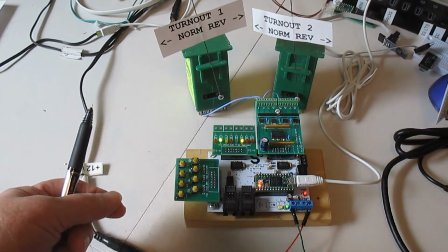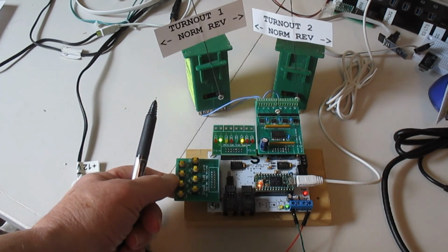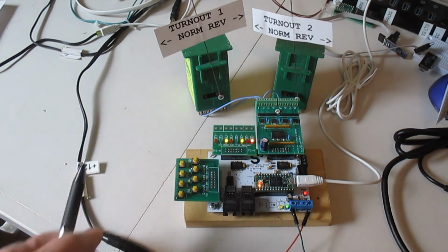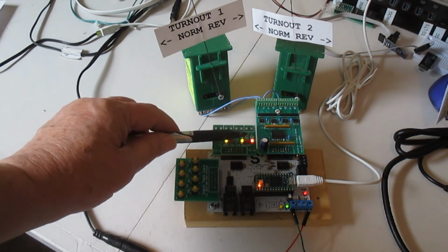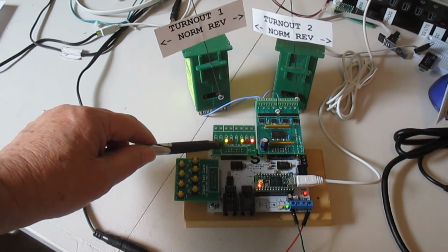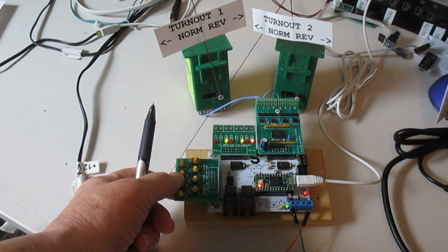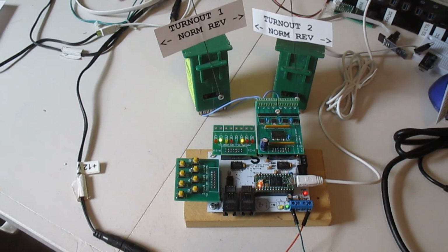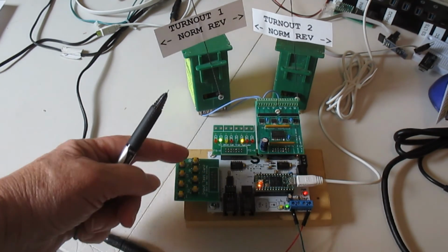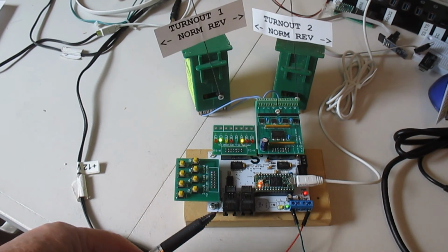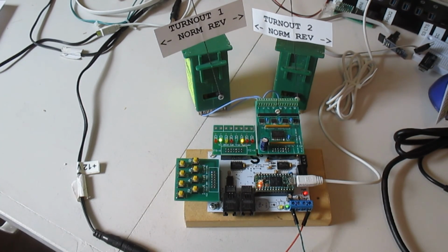The one condition that sets the signal yellow is when block 2 is vacant but block 3 is occupied. And you notice when I set block 3 occupied, the signal then goes to its yellow mode, and if I mark that as vacant, it goes back to green. Basically, that's the function of this particular junction setup that we have. And again, it was all done by point and click and downloaded to the card.